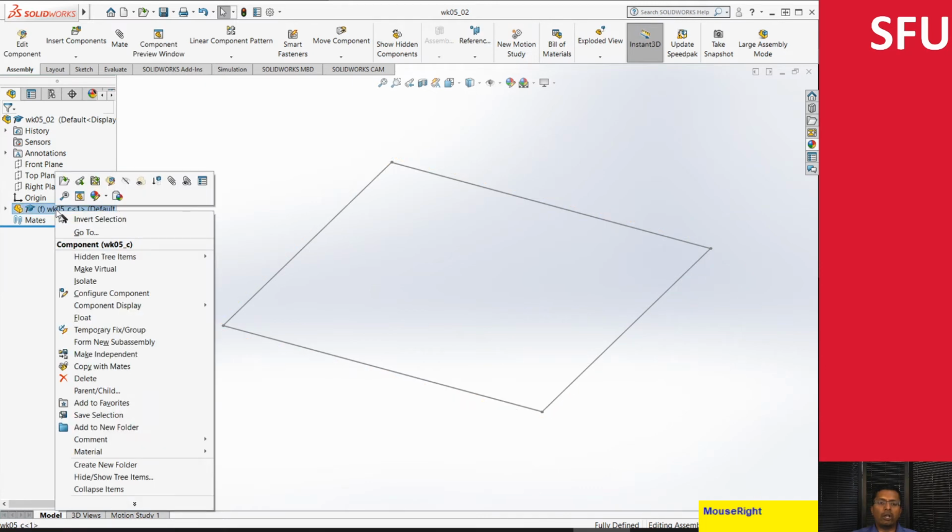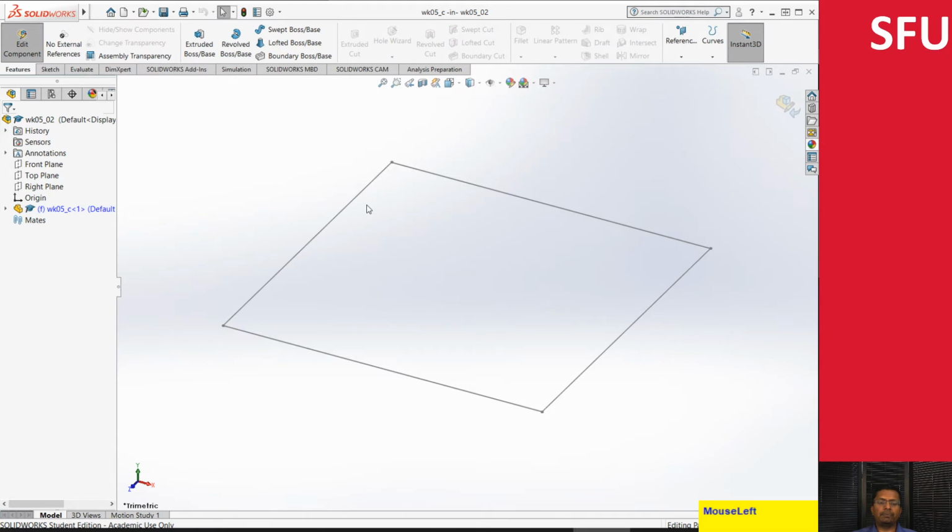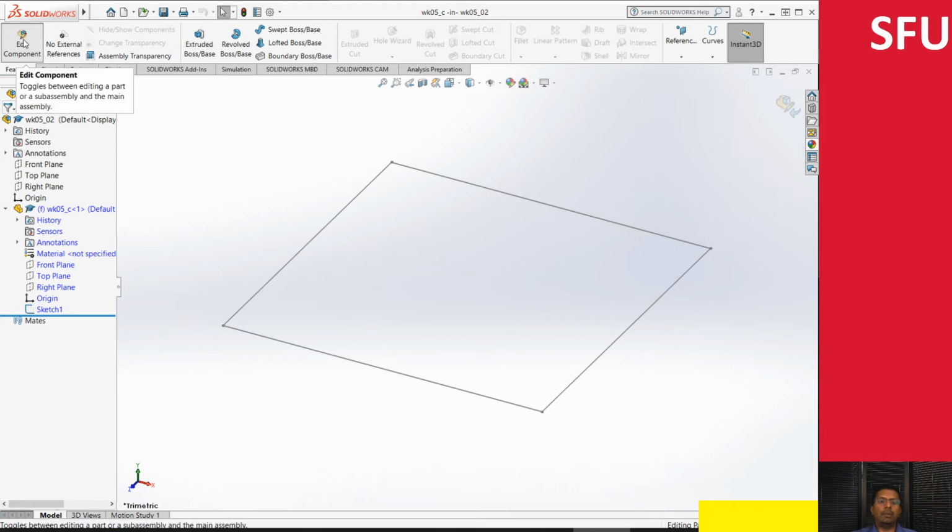So what I can do is also right click. If I didn't want to open the whole part, I can right click and click on where it says edit part. What it does here is open the part within the context of the assembly. So I have this option here, edit part, and all of my other familiar menu options just switched out a little bit.